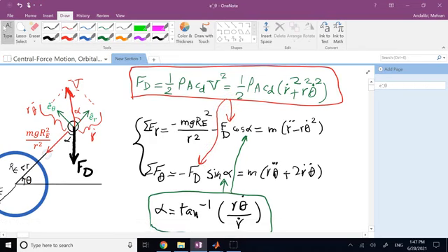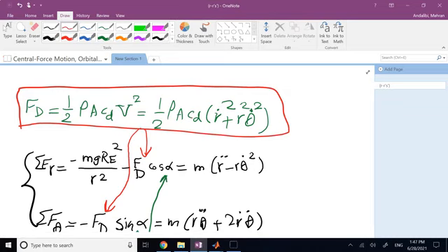So you see your equations are going to be highly nonlinear. And worse than that is this part here. These terms, rho, A, and C_D, in many simple applications like a trajectory on the surface of the Earth, you might consider them to be simple constant numbers. They are not. C_D, the drag coefficient, does depend on the speed. So C_D itself is not a constant number.